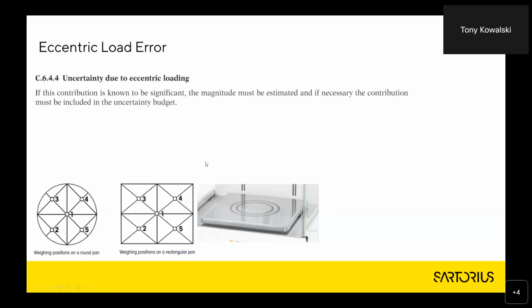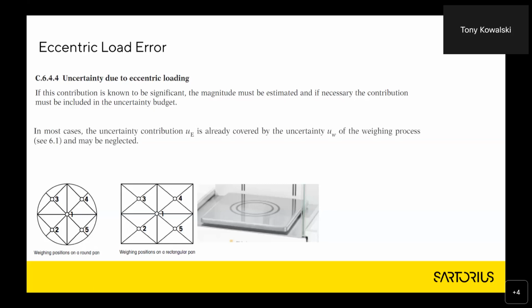In a mass comparison, we don't really want to stress by testing at this distance. We want to test within the range where we'd normally place our weights. So for a mass comparator, whether it be a rectangular or a circular pan, we start in the center, and for convenience, we quite often tare. We take the weight and we place it within the circle that we're looking for, the size of the weight to compare.